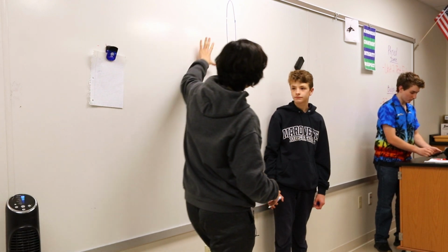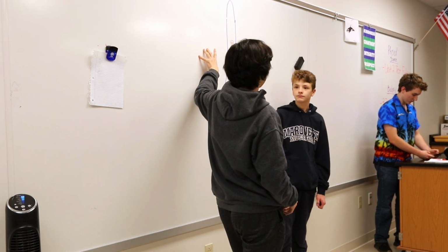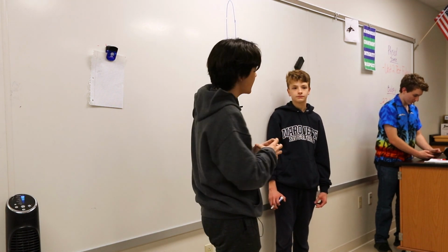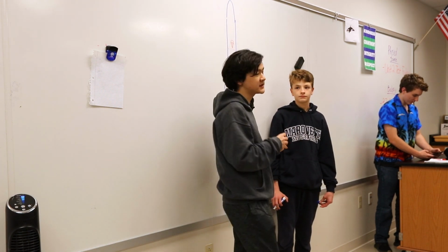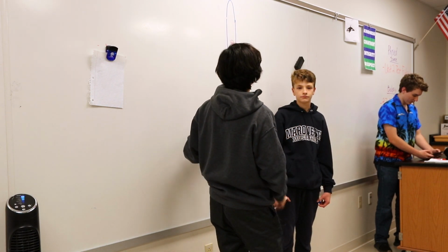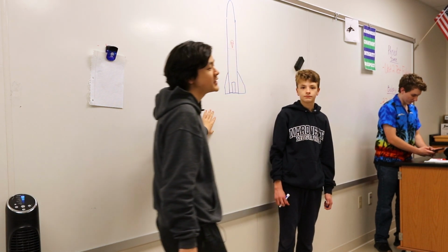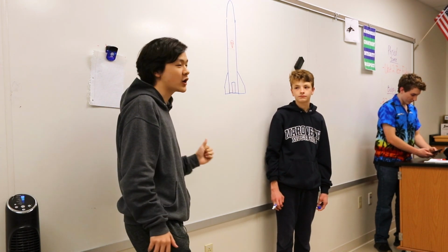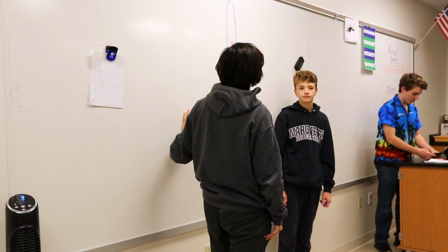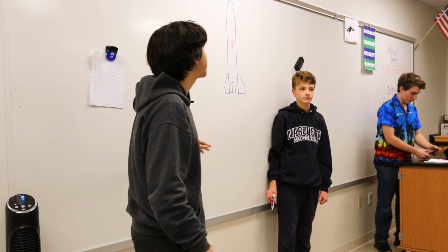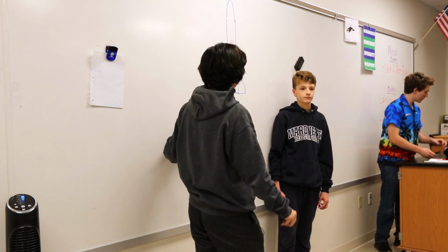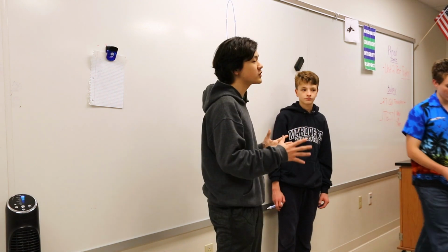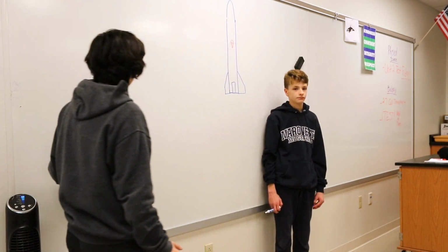But the next part, the main body of a rocket, is going to be called the fuselage. This is basically the tube that houses most of the rocket's components. Here at Astral Orbit, we typically like a clear fuselage. We use a material called polycarbonate. It's a plastic, and it just allows for ease of inspection and maintenance. That's pretty much all there is to the fuselage. It's just a structural component that holds the rocket together.